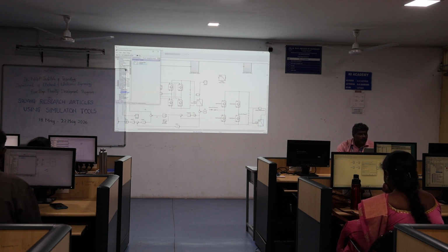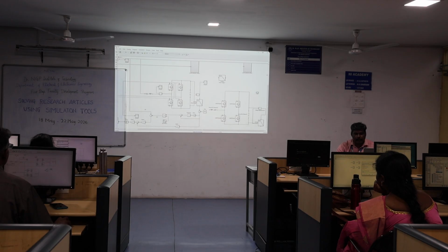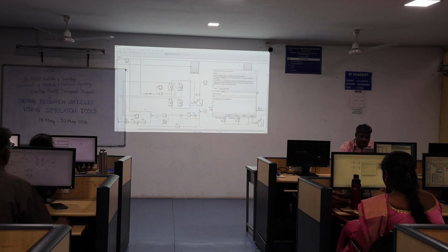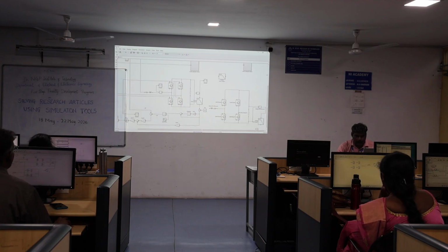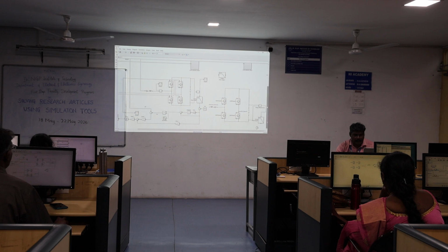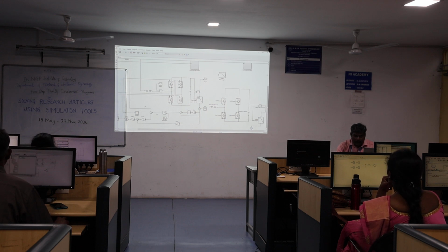Go to Simulink. In Simulink you have a sum block. Take the sum block and double click. Just convert it to minus and plus, so you can take the difference of the two values. Control R. The measured value is plus. So the measured value you can just connect after the analog filter.